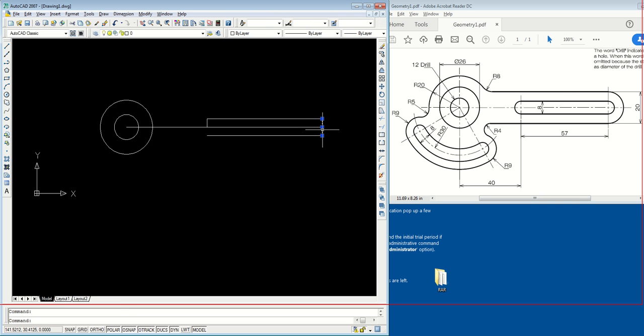This line is not one of the basic lines that I use. This one is also not. So I can go up to draw this line also. Yes, from this point to this point, it is in the center line of these two points. So from here to here it is 20, and from here to here it is 10. Yes, so if I go up again from here by 10 and enter, then I reach this point.